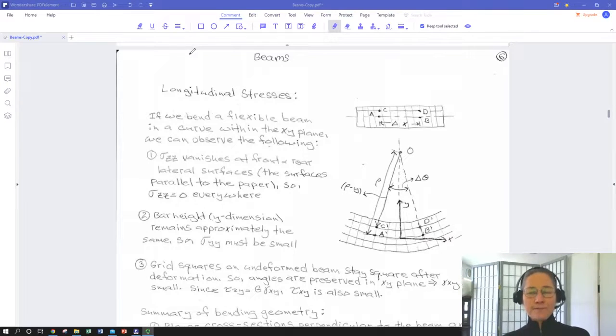From that standpoint, we can also have axial or longitudinal stresses due to just literally axial loads, like the beam being stretched in the axial direction, and that was represented by our normal force N at any cut section. So this would be in addition to that normal force, but ultimately generated by our big M at any x